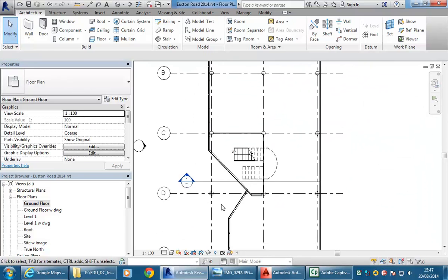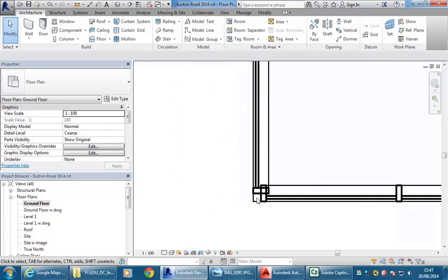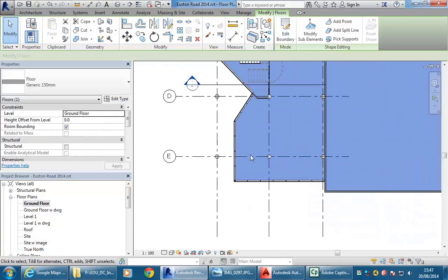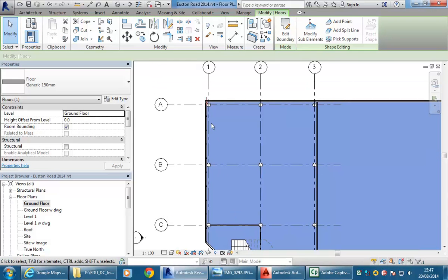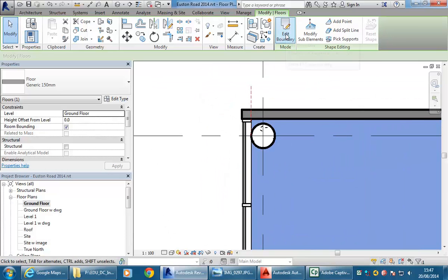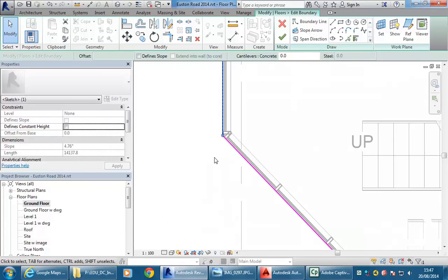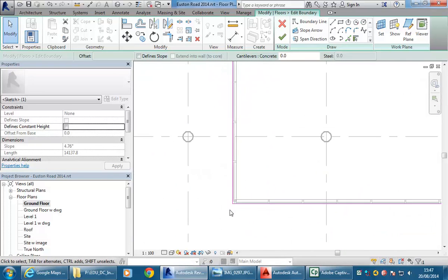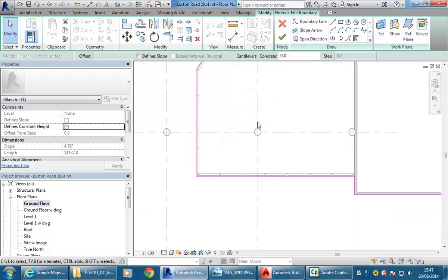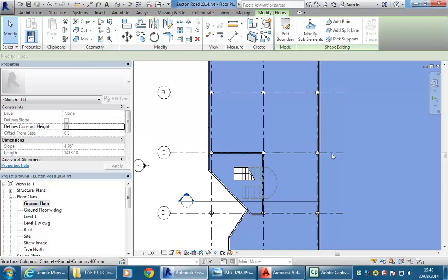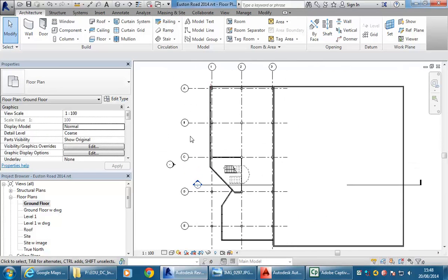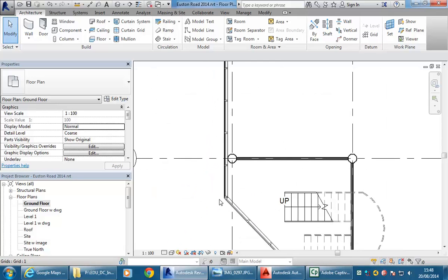And then the floor is a bit hard to see, but I can find it there on the corner. And so at this point, you'd want to start thinking about the edge of that floor, and once you go to Edit Boundary, you can just adjust the edge so that it sits at least to the front of the curtain wall. Okay, so that's pretty good. Okay, so that's the basic setup you'd want before worrying about the divisions in your curtain wall panels.